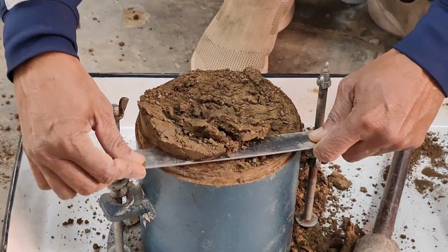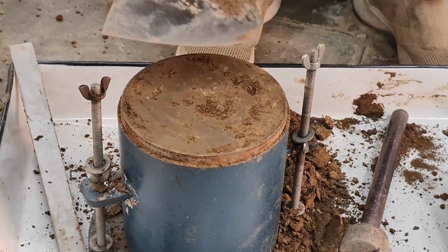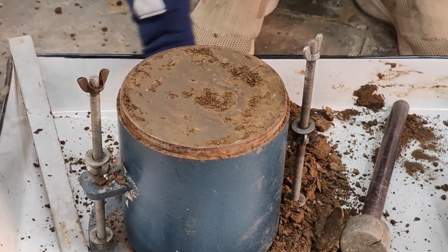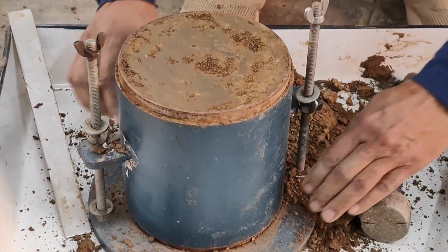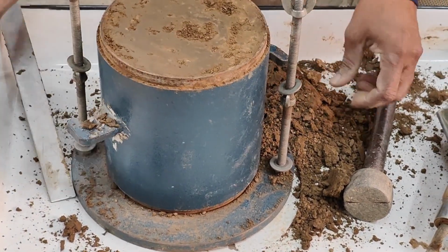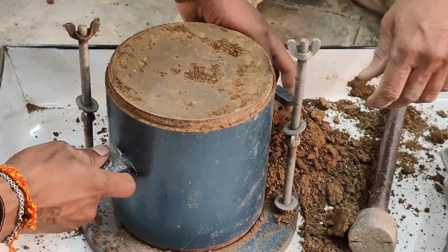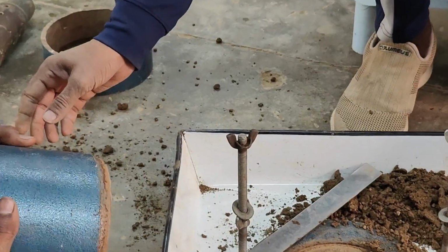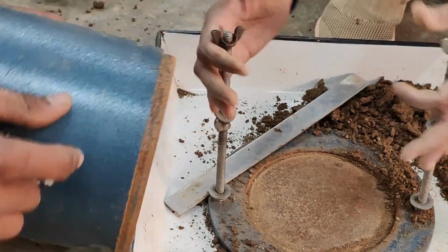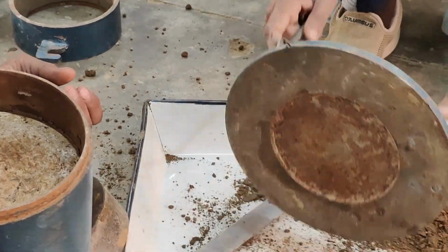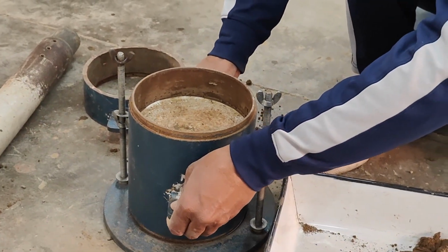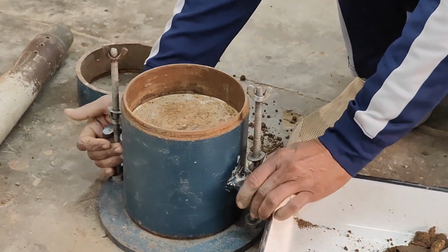Trim the compacted soil carefully by means of a straight edge and remove the extra soil, and any hole that may be there on the surface of the compacted soil by removal of the coarse material should be patched with small size material. Remove the spacer disc now and place one coarse filter above the base plate.